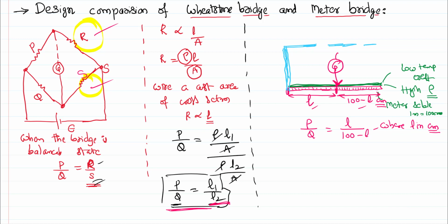Again here we'll leave a little gap. This is again a copper strip. You might have seen this kind of arrangement in our laboratory also, right? In one gap we connect a resistance box. We can keep a particular resistance, that is P, but we keep a resistance box, therefore we can do experimentation in different ways. So we connect a resistance box. In the other gap we connect a resistance X, which we can find out.